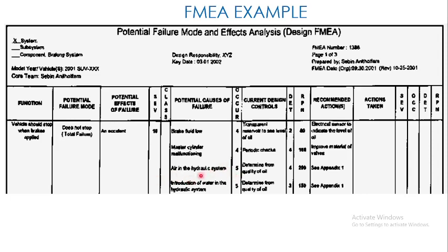Again, you can have air in the hydraulic system. And apart from that, another cause of failure is the introduction of water in the hydraulic system. The brake oil has some sort of contamination of a chemical or water. So these are the occurrences.